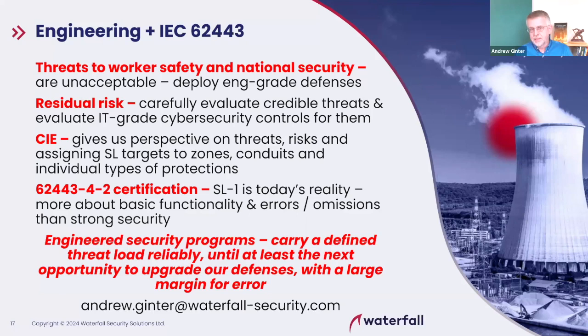There is a longer answer. There's always something that needs to come back in. So the classic example is predictive maintenance. The turbine vendors do not press a button and control the turbine from the cloud. What they do is they pick up the phone and they call and say, you've got a vibration problem building up on generating unit number 3. Can I have an hour Thursday to work with you to fix the problem? Sure, we schedule them. 3 o'clock Thursday comes, we call the vendor.